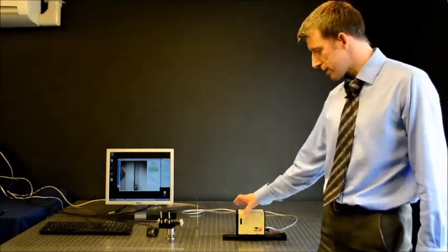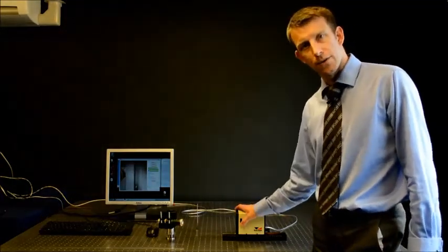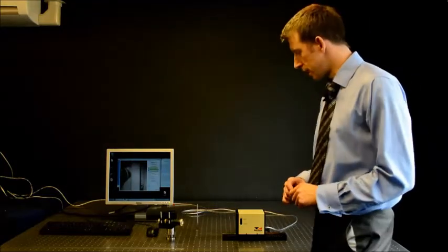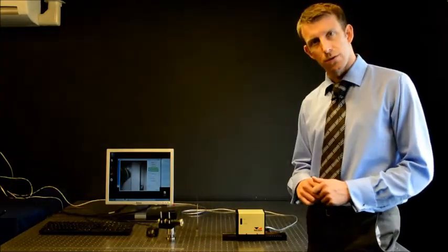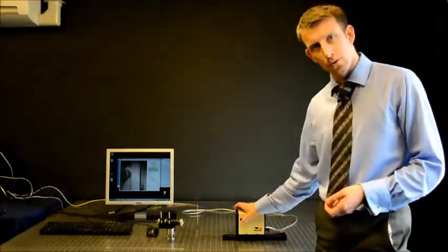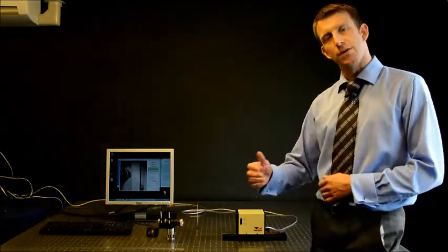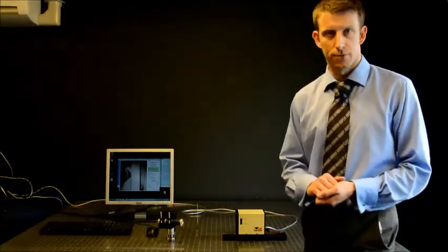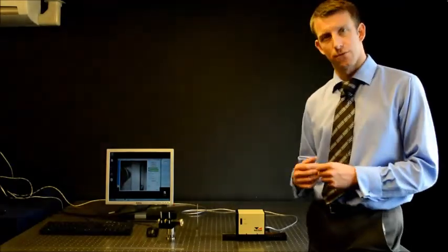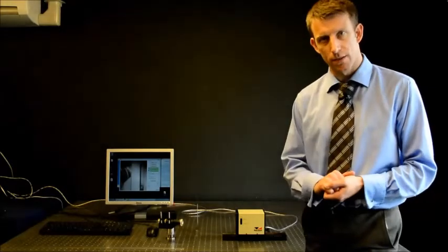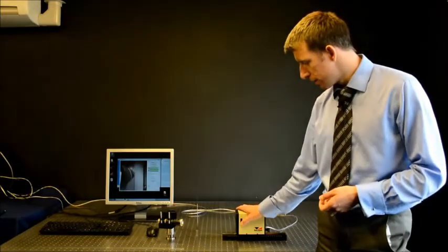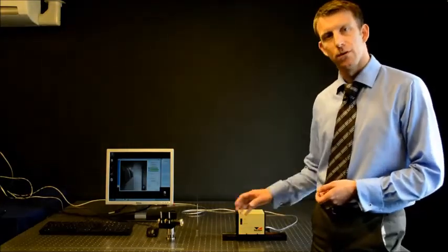The PSL Profiler has at the entrance an iris diaphragm, which can be used to close or to open effectively the size of the lens. But the use of this should be restricted to only the most extreme cases. The reason being that in closing this iris diaphragm, one increases the depth of field, so everything appears in focus. Since the principle of the PSL Profiler is to determine where the source is in focus, where the apparent source is located, this is no use. So one should always ensure that we wind the iris diaphragm to the upper position, the open position.